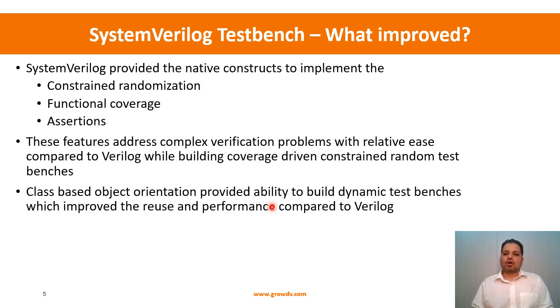And this would not have been possible with Verilog, because in Verilog, before we even do the compilation, we have to commit to the number of modules that need to be instanced and how they need to be connected. Everything I need to commit right at the point of compilation, whereas that was not required with SystemVerilog. So this is a sort of step improvement in that particular direction compared to Verilog.